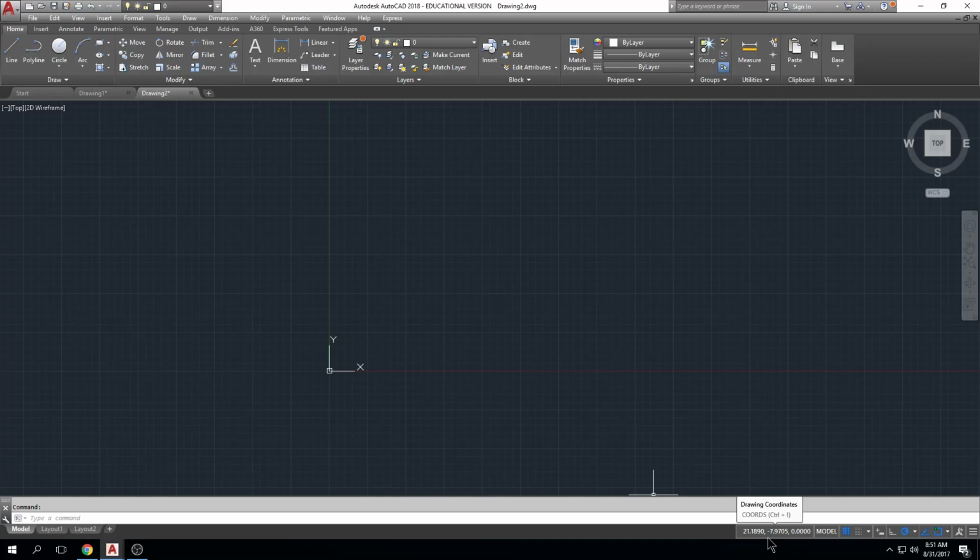For this class you really just have to know what this means. You have to understand the theory behind it to know how AutoCAD organizes itself. After this week, where we will learn how to input coordinates according to the system, you really won't have to pay attention to it anymore. Today we're going to input things according to our origins, just so that you understand how it works.